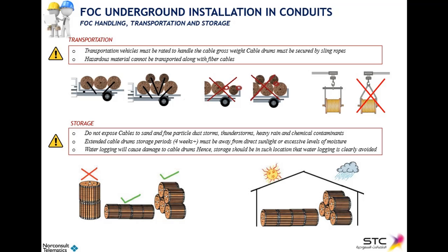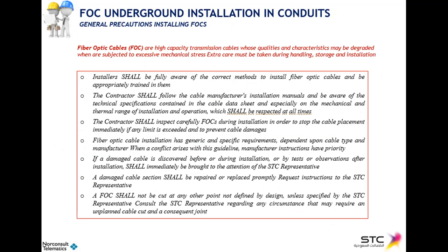We are not accepting warehouses where you expose the cable drums and other ODM material to the weather conditions. They must be sheltered somehow. We are not saying that these have to be in specific sealed rooms or whatever. We are saying that they must be protected against sun and rain. One more time, insisting on the fact that storing can only be done by placing the cable drums in upright position.